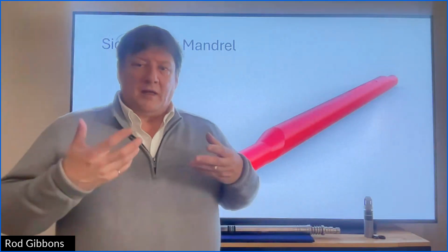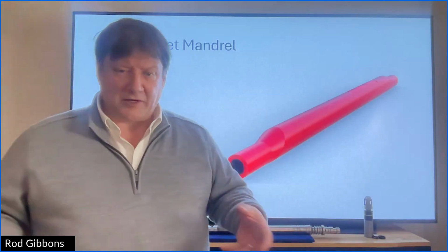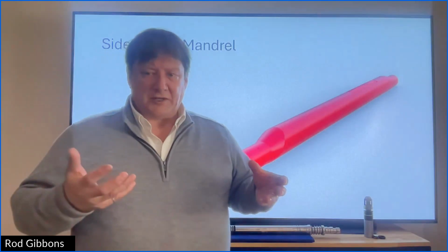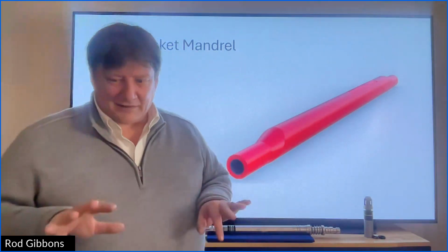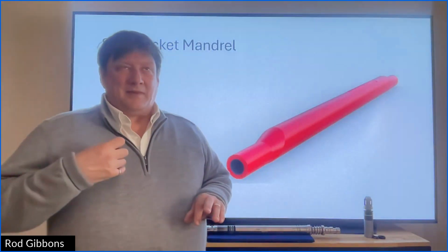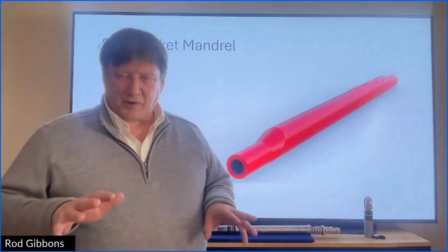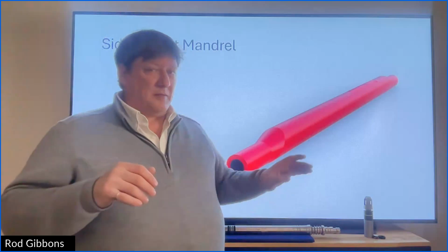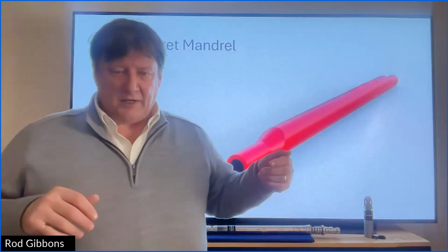You should be swapped over from drilling mud to clear brine or completion fluids, whatever's good for running the completion. You want to have nice clean fluid, so you're not going to have reservoir fluid in there. You have to have your well killed and conditioned before you run your completion. So we can live with communication at that point.